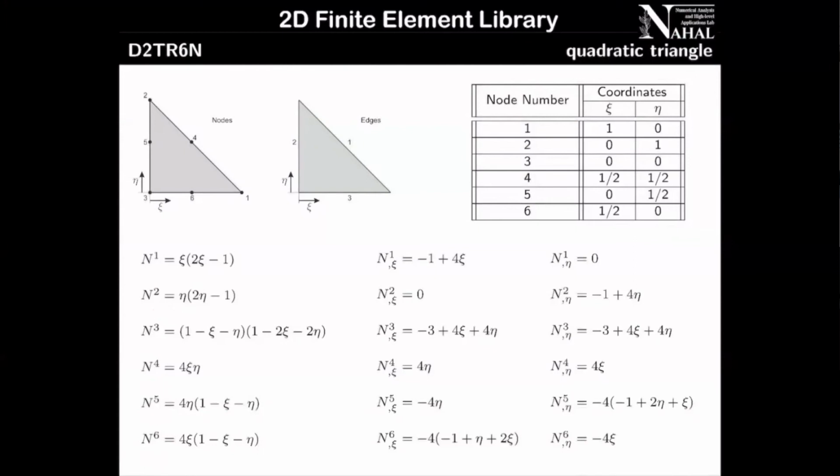As you can see, again, here, when you talk about triangular elements, when you say they are quadratic, they are really quadratic. Okay, they don't have that higher order. So a quadratic quadrilateral element gives you something of order 4. Here, actually, a quadratic triangular element gives you something that is quadratic, of order 2. All right, so these are the elements themselves.